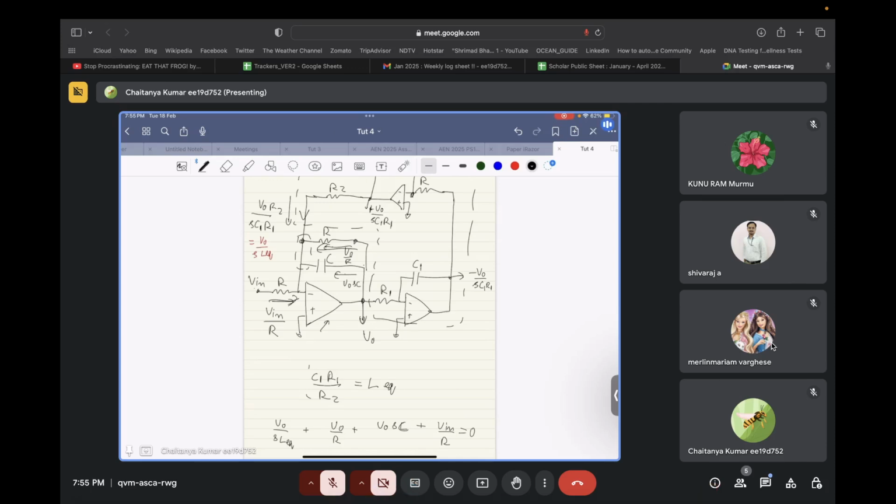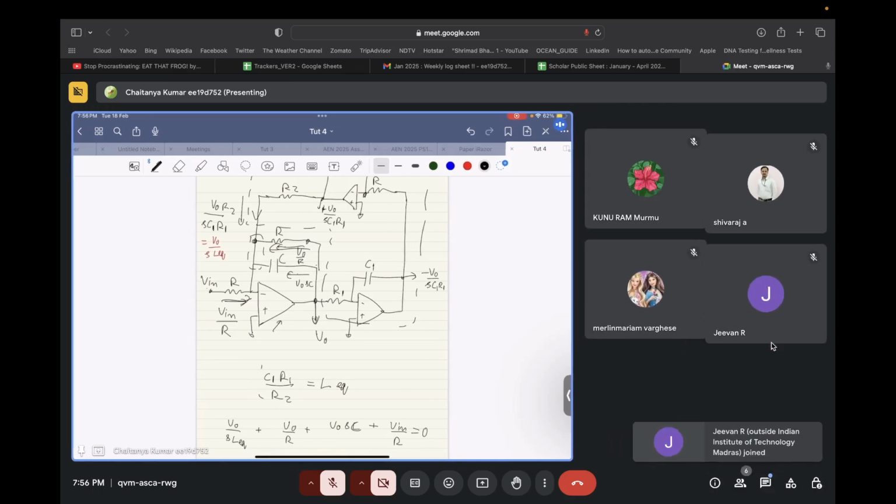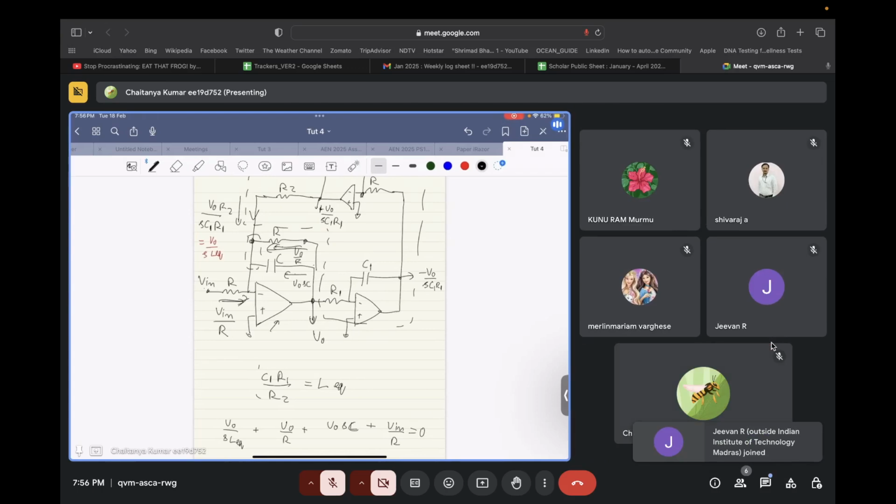So here, the physical motion of electrons was causing the noise, right? In capacitance, you don't have the actual current, you have the displacement. I think you might be familiar with the concept of displacement current in Maxwell's equations, which you might have studied. You have the displacement current, and that's radiation that can't generate noise. In inductance you have a resistance-less coil. That basically generates flux, and that's how it stores the energy. So there is no noise. Energy storing elements don't have noise, only the resistors have noise.